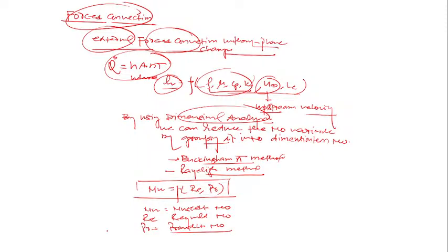Now, the problem again is: what is the functional dependency of the Nusselt number on the Reynolds number and Prandtl number? For this we should carry out an experiment. Now it is very easy to carry out the experiment. Why? Instead of observing the effect of six parameters on the heat transfer coefficient, it is now easy to observe the effect of two parameters on the Nusselt number. Clear? Now instead of changing the density and velocity separately, we simply change the Reynolds number. Is this clear?